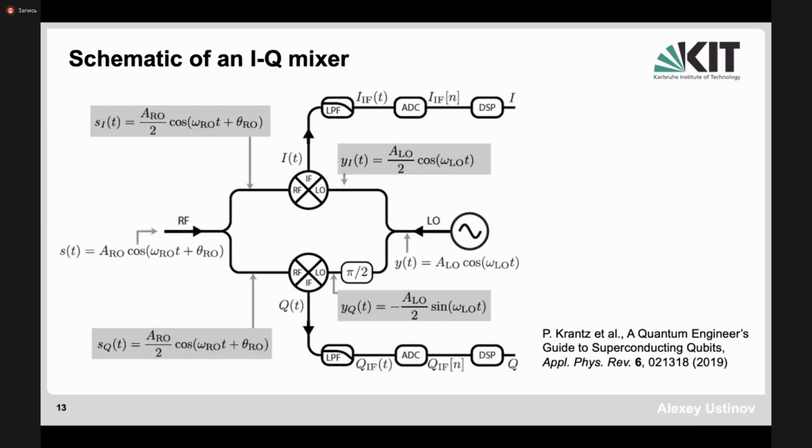Now, what is the IQ mixer? I just told you that it has the amplitude and the phase, but in fact, it's nothing else as the device shown here. So it has actually two mixers in one. And every mixer has a local oscillator input and RF input. They are exchangeable. So basically, it's a device which can be used as a modulator or as a mixer. For example, one can use local oscillator to make the particular profile at the output. So this arrow will be reversed here. And that's what I showed you in the previous slide.